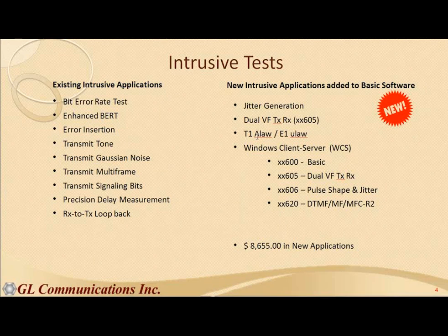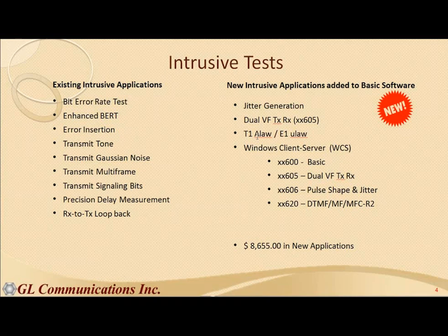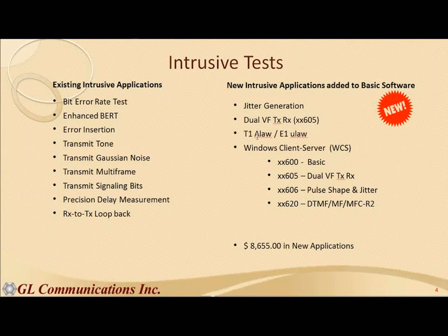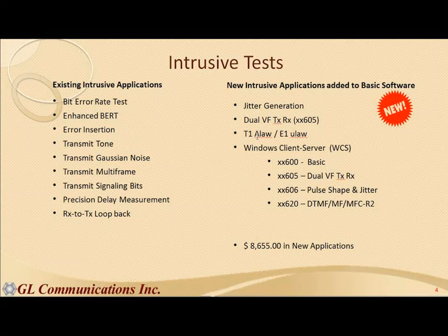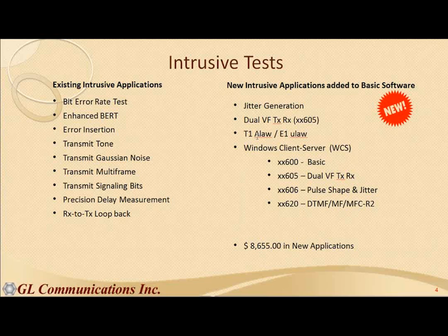There are a lot of supported applications like transmit tone, record and playback, DTMF digits, spectral display, oscilloscope, all those applications are supported. Basically, this option allows A-law on T1 and mu-law on E1. Normally, this will not be applicable for most applications because the standard is for T1 to have mu-law and E1 to have A-law.